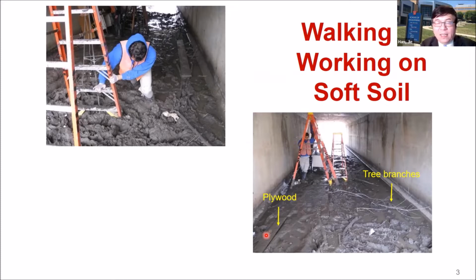And then he said, well, I learned some geosynthetics from you. How about we try geotextile? Then we placed the geotextile on top of the soft soil, and he walked on it and still sank in, as you see here, those are the footprints of him. Then we tried the last one, geogrid. We placed geogrid, that's what he's standing on, and he is working on the soft soil. Now, what's the difference between geogrid and geotextile? Geogrid, as you know, has bending stiffness. Even though the bending stiffness is not very high, that's enough to support the person working on the soft soil.